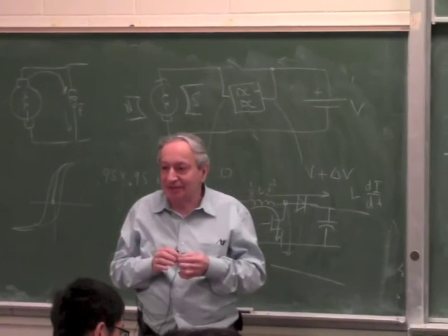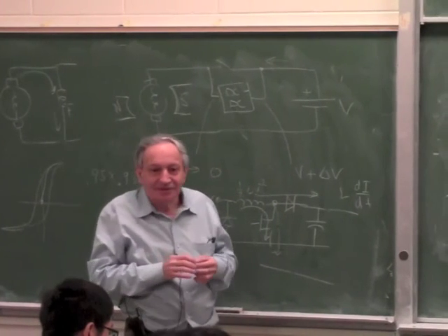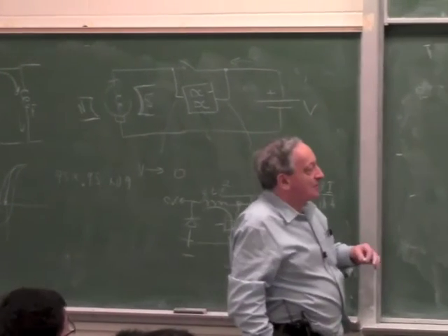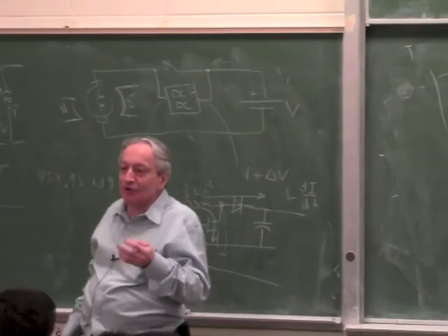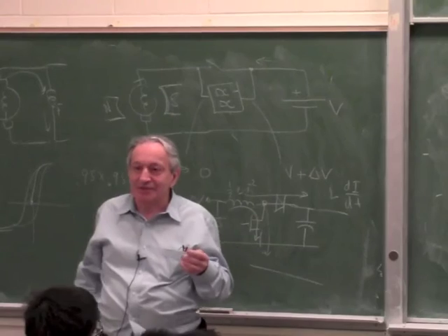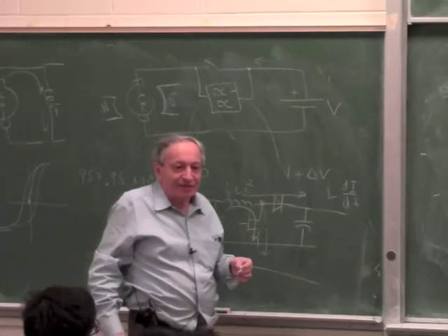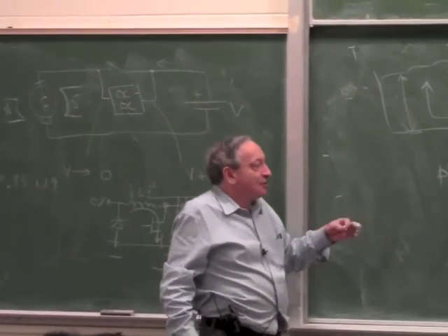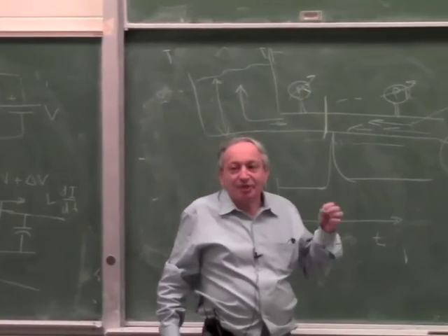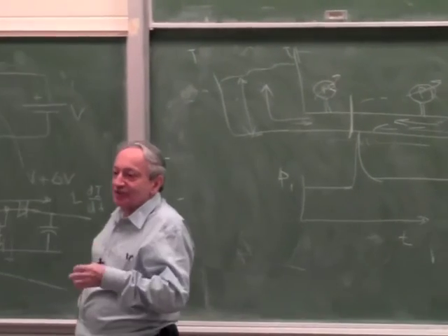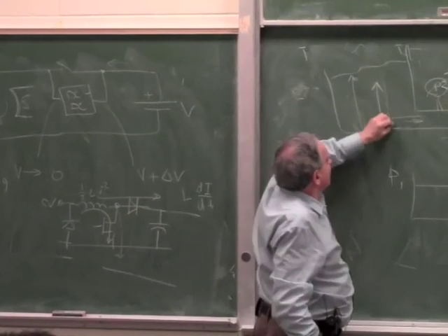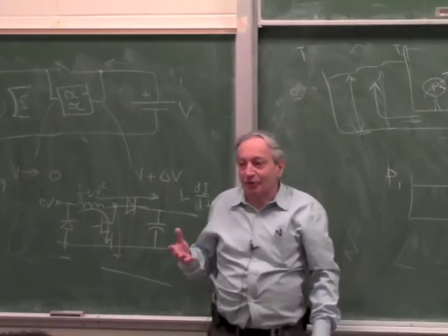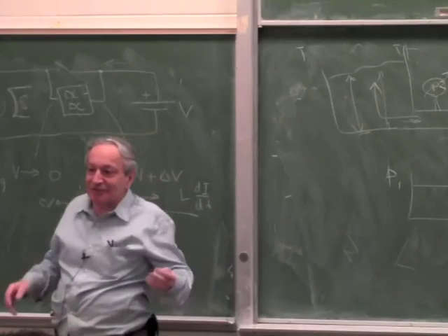a non-electrical servo. Okay? So remember again the analogy, because the only non-electrical servo you are likely to have to work on is fluidic. I mean, there's other things, but you're not very likely to work on them. So remember the analogy: in a fluidic servo, pressure is the same as voltage, flow is the same as current. The static pressure here is basically a voltage. It's like a back EMF in this case.